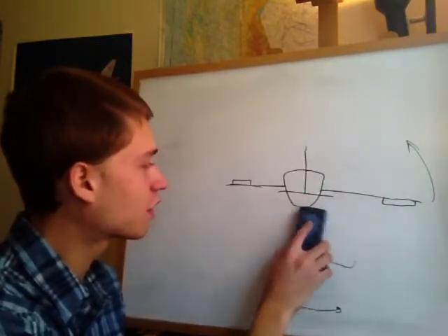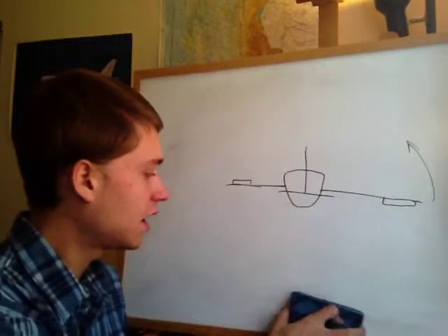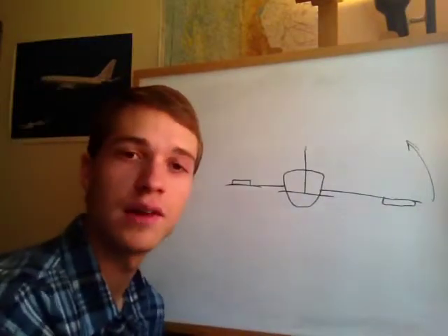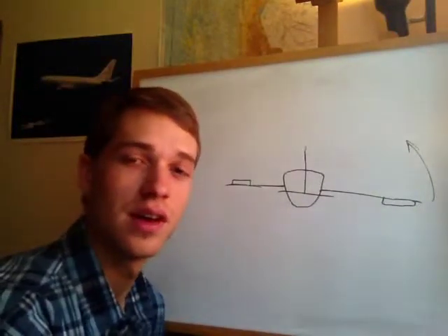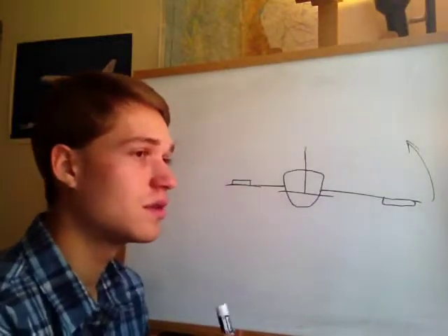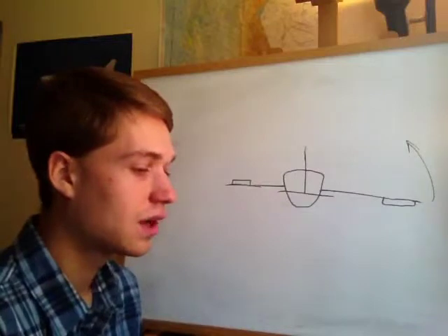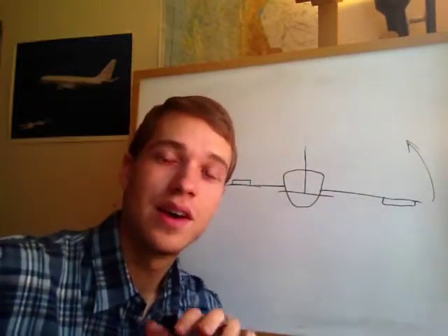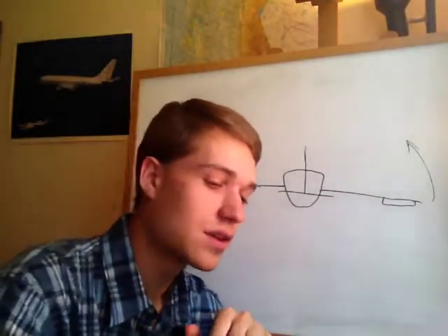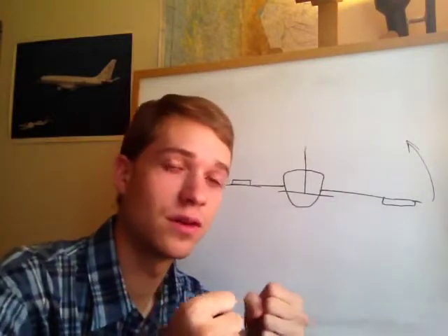Alright, so that's how we overcome adverse yaw, and it's something that actually becomes more pronounced when you're flying at lower airspeeds. And so you're going to have to use more control deflections, and here's actually something that I need to point out. And when you're flying the airplane, you are actually going to be able to feel your controls.